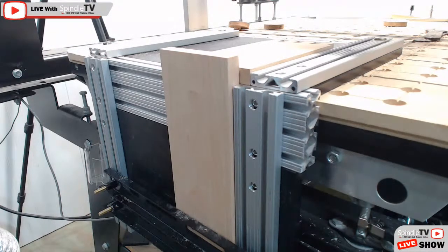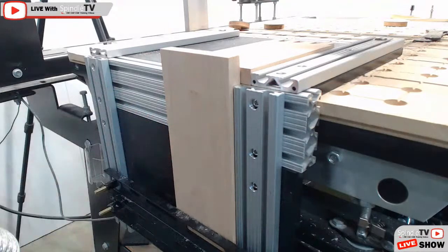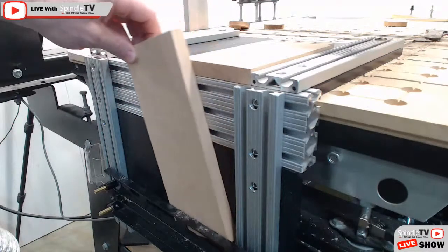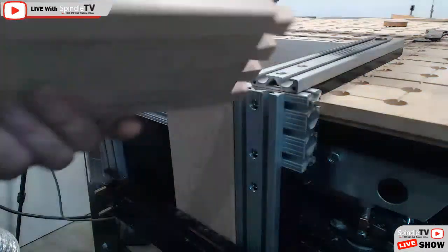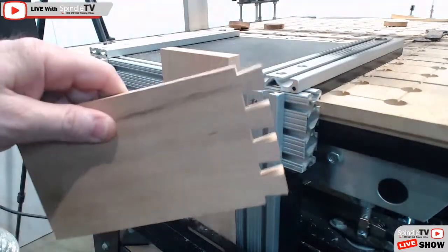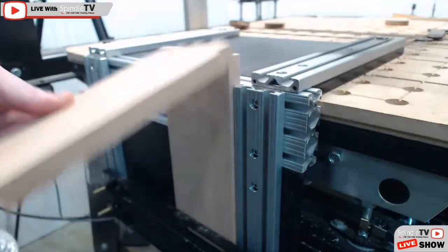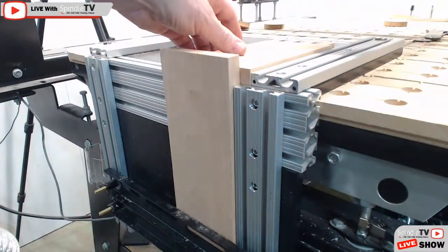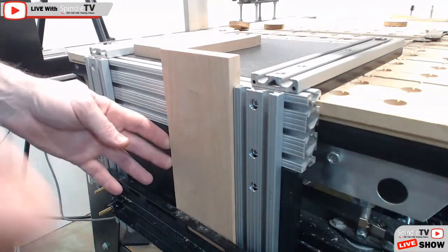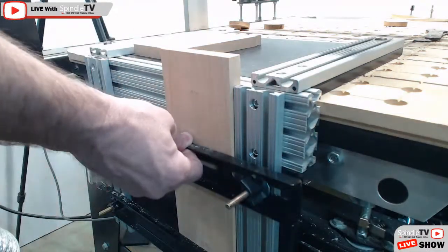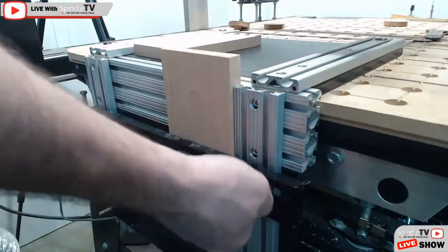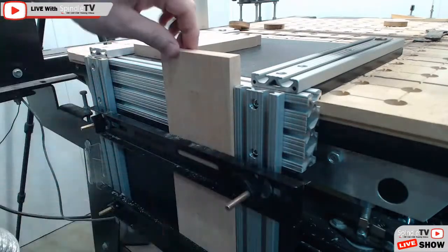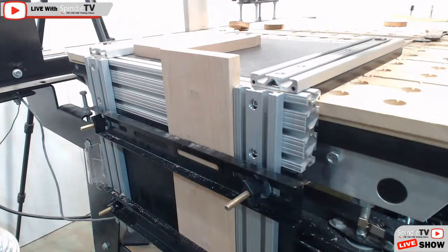It's very important that you pay attention to your setup. That's why we do test cuts and everything. I usually don't do test cuts on good wood, but I happen to have some scrap piece of cherry from the same stock that I'm working with, same thickness, same size and everything. So it was ideal for me to test the dovetails on. All right, so now that I have this in place, I'm simply going to slide the clamp into place and lock it down. And that's it. Once I'm locked down, I'm ready to zero out and cut and everything.